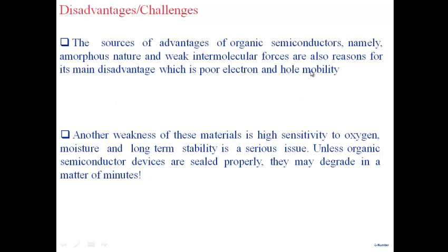All right. By the way, poor electron and hole mobility I'm mentioning, but people have demonstrated, all of you may have heard of RFIDs, and one of the standards for RFID is 13.56 megahertz. People have made RFIDs using organic materials which can operate at that frequency, at 13 megahertz. So you can reach speeds of megahertz as well. But with many of the circuits that you'll make, even if they switch at a few hertz, it's fine. You can make applications out of it.